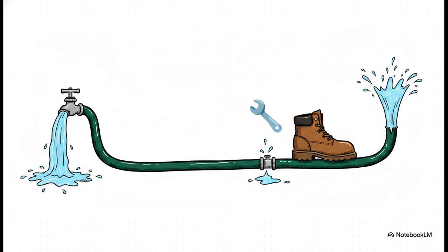Now, if you're having any trouble visualizing this, just think of a normal garden hose at your house. The open tap end, which is always running water when it's on, that's your continuous grade. The screw connector attaching the hose to the tap, the one that weeps just a little bit occasionally every time you use it, that's primary. And a random puncture from, say, accidentally stepping on the hose, which is rare and definitely unexpected, that's secondary. It's the exact same hose, just 3 completely different leak behaviors.